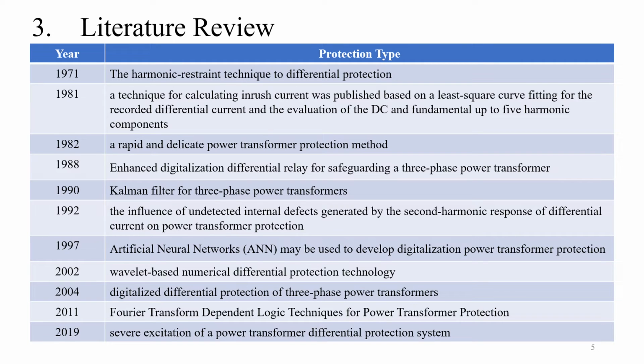The non-zero differential current produced by power transformer energization and that produced by an internal fault are well matched using this method. Using the second or a higher harmonic component, this method has been employed to provide quick defect detection.